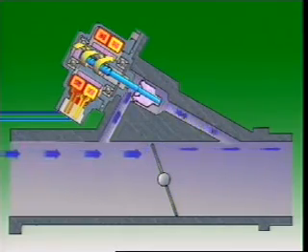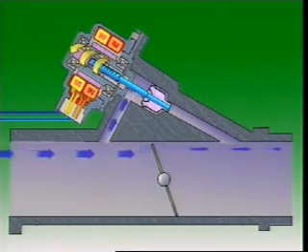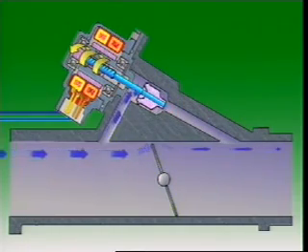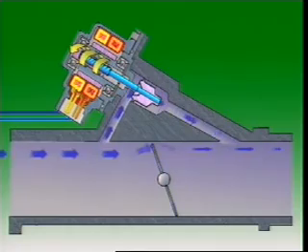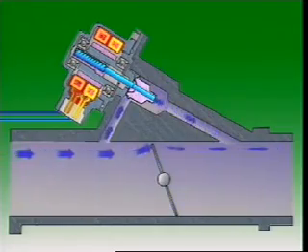The pintle turns in forward or reverse steps, numbered from 0 with the bypass air passage fully closed, up to 255 for maximum airflow. Such a large number of steps allows the pintle position to be finely controlled.